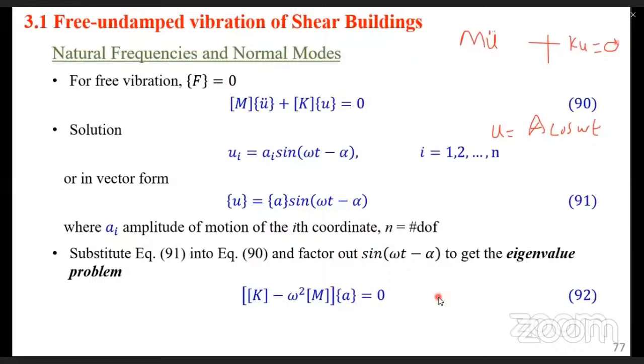Because you studied this in a previous math course, you might not delve so much into this eigenvalue problem, but you should know about it. For those who are inquisitive enough, when you did your modeling in Abaqus, if you went to the message file, or is it the report file, and opened it, if there was an error in your analysis, you might see the issue of negative eigenvalues.